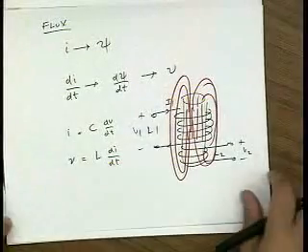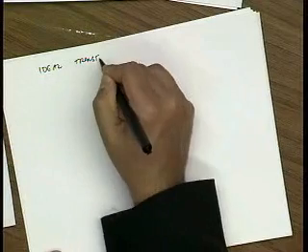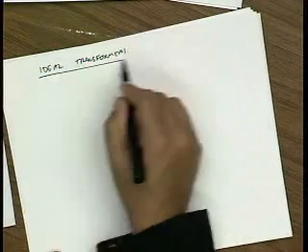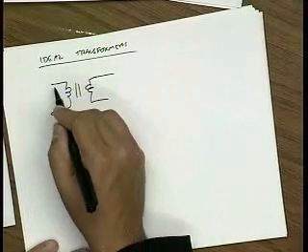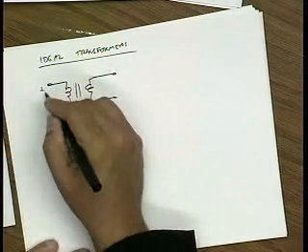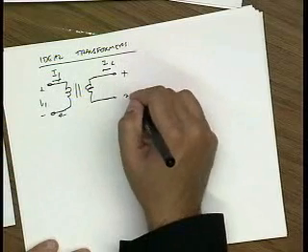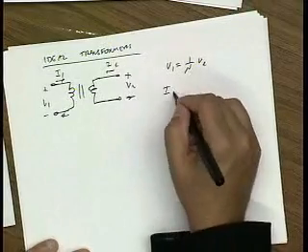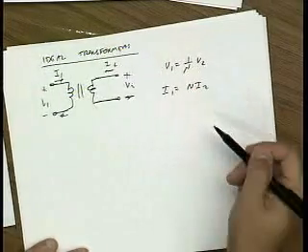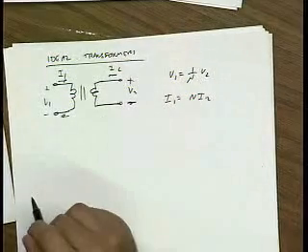Okay, hopefully this is all a review. Let's also review ideal transformers. So ideal transformer, the way we draw it is we put these two bars next to these two inductors. And basically the relationship for an ideal transformer is that we get some voltage scaling and some current scaling. By conservation of energy, I just need to tell you that there's voltage scaling, and automatically the current scaling has to look like this.